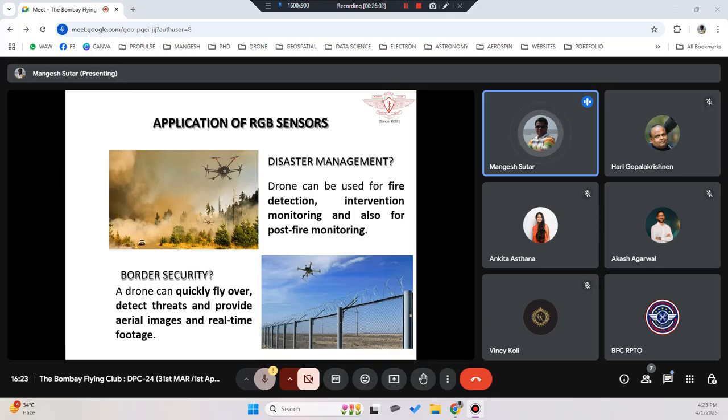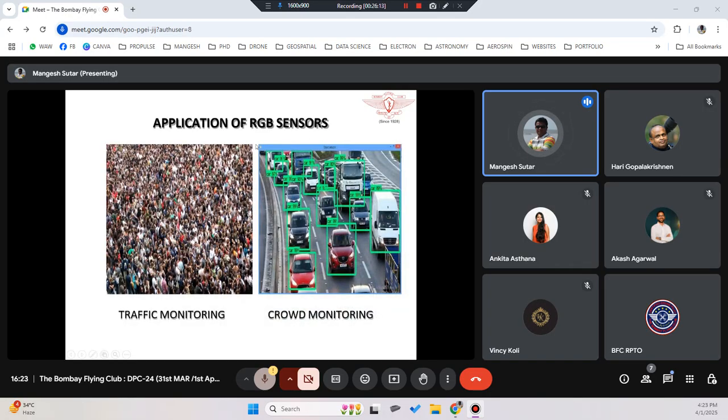But in phase 3, they wanted the camera itself to be AI enabled, so that it would pinpoint and show me exactly the way it was showing here. If I imagine this is the picture I'm seeing of the tower, it should show me then and there wherever there is any missing part or defect on the tower, like a nut bolt missing, a jumper member not connected, a danger plate or number plate not there, or a bird nest on the tower.